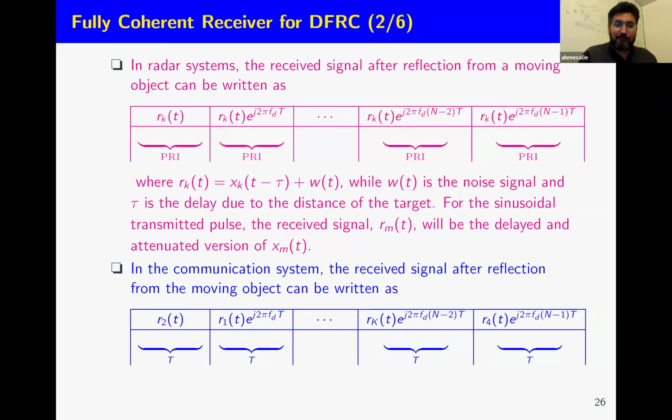So how can we solve that problem? Here we have multiplicative noise. If all the values are +1, there's no problem, right? But here they are changing, so it becomes multiplicative noise. Due to multiplicative noise, after applying FFT, we cannot estimate the Doppler shift, and if we cannot estimate the Doppler shift, we cannot estimate the velocity.